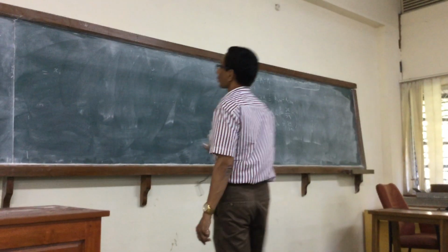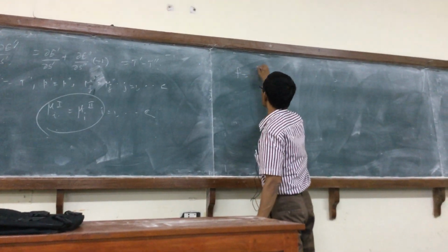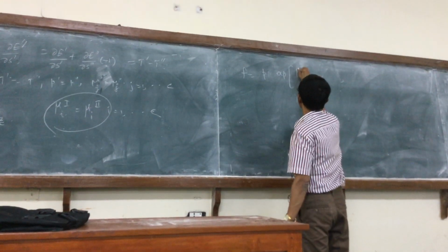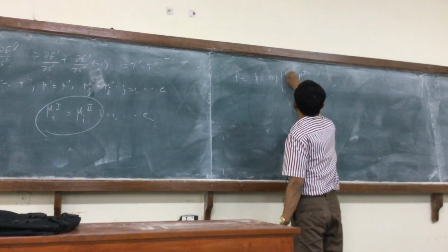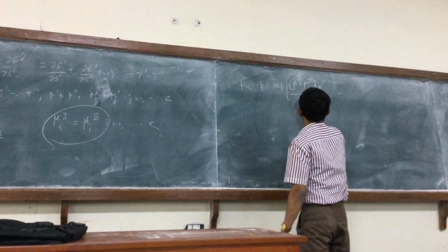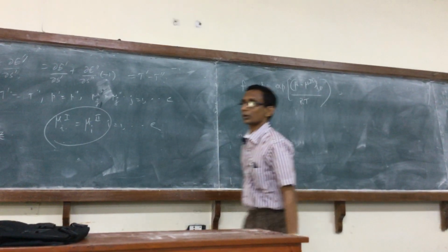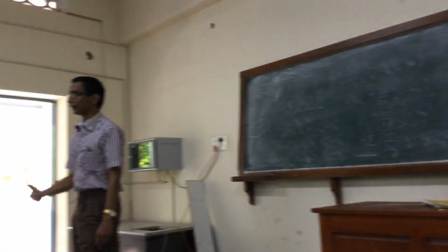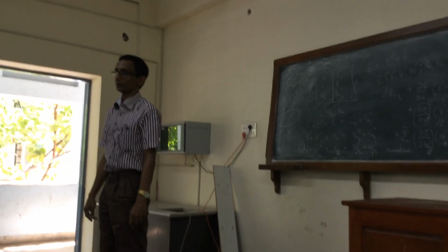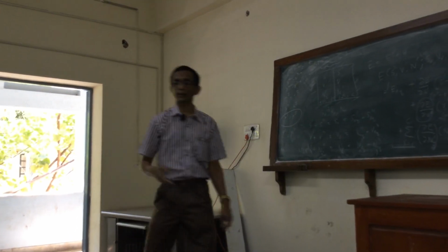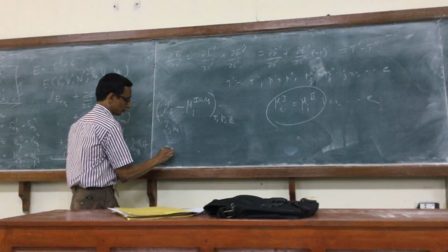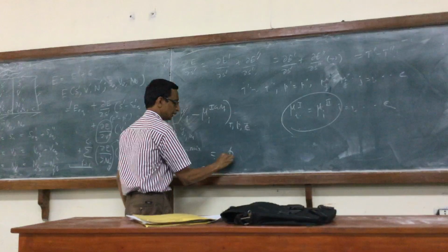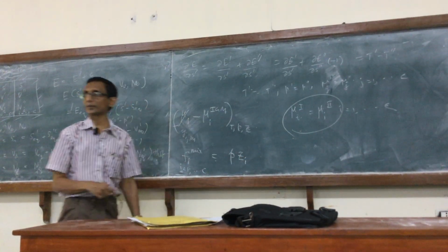If you recall, for the pure component, the fugacity was defined as P times exponential of the departure, evaluated at the same temperature and pressure. This is the definition of the fugacity. Now we can define, for the C component mixture, the fugacity of each of the components in the mixture, and that definition now I am going to give. For i equal to 1 to C, it is P times Zi, where P is the pressure of the mixture,